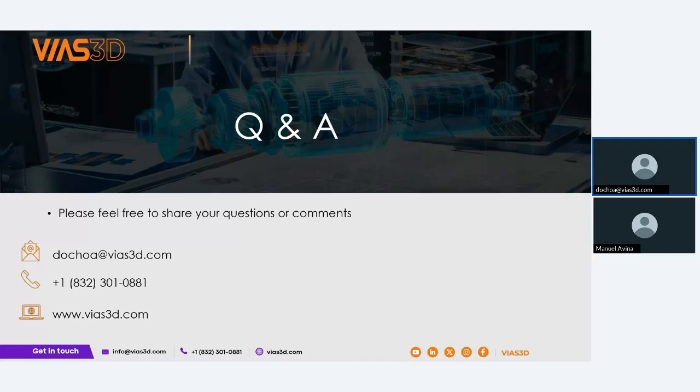Okay. So there are a few of them. I would say first check the PCB layout. Okay, how much accuracy do you want to put on that 3D model? Do you want to add simplification or not? I would suggest adding a certain amount of simplification and keep it without simplification on the important parts. Okay, where you already have a heat source created. Okay, just to understand what is happening inside of those many layers and inside of the substrate.